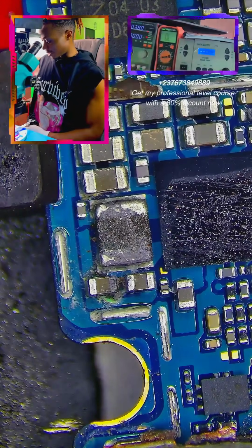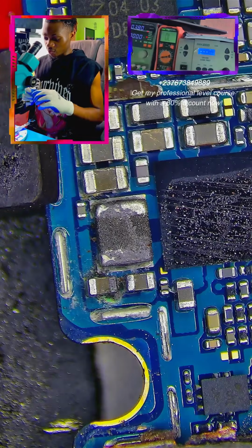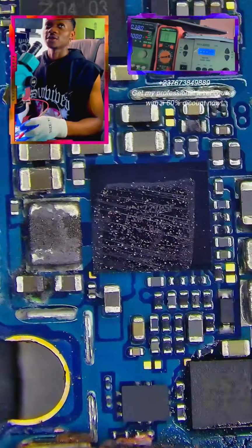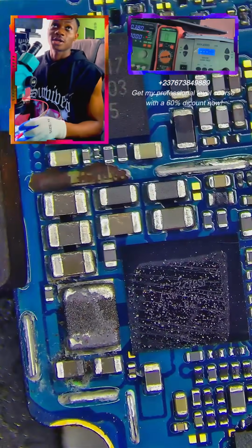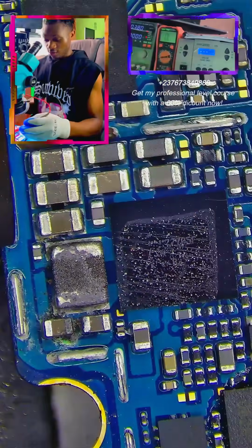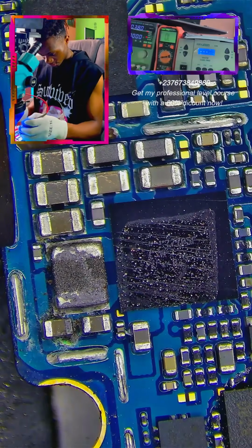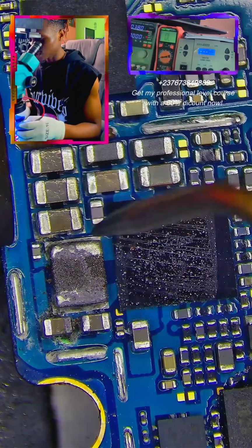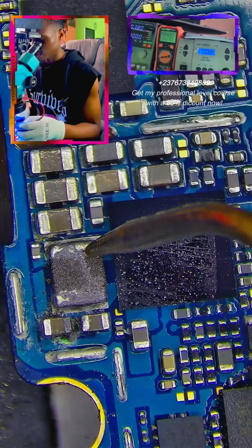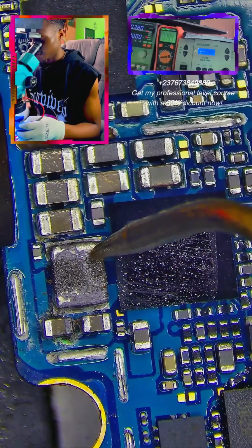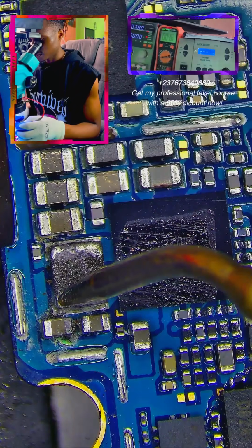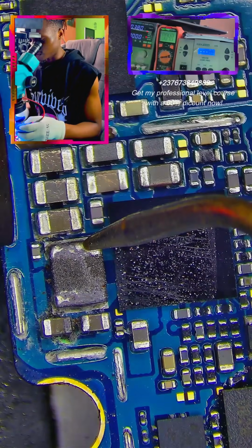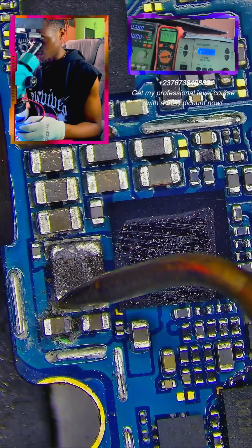Keep in mind that I said this is where you have to start troubleshooting this current leakage. Not in all cases will you open the phone and see that the VPH line is shorting, but that should be the first line you check when you are having such a current leakage. So we perform a cold test. The red probe goes to the ground and we use the black probe to test the VPH inductor here. When you are testing this, you don't get a beep because this is the VPH line and it should give a reading, not a beep.